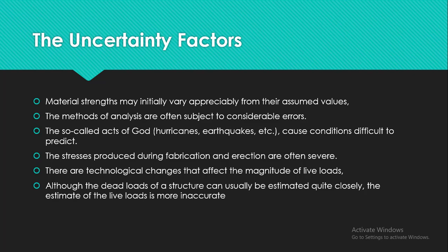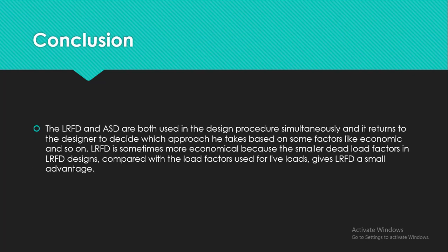So, our conclusion: the LRFD and ASD are both used in the design procedure simultaneously, and it is up to the designer to decide which approach to take based on factors like economics and so on. The LRFD is sometimes more economical because of the smaller dead load factors in the LRFD design compared with the load factors used for live loads. So that gives the LRFD maybe a small advantage.